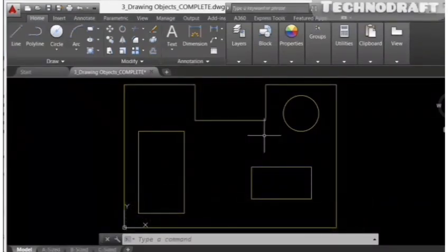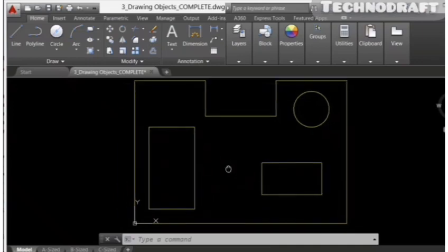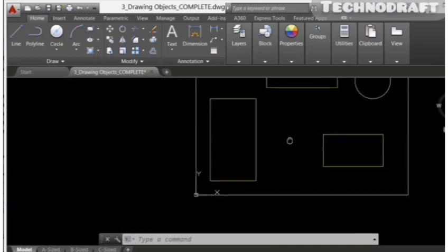And now the next one I'm going to place in the rectangle on the left hand side. So I'm just going to pan upward a little bit so we have it nice and central on the screen, and I'm going to use a tangent circle. Before I do that, make sure that your tangent snap is switched on.